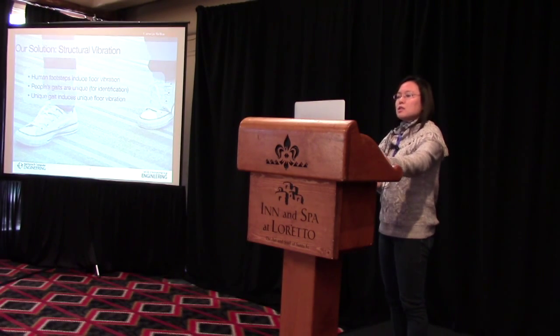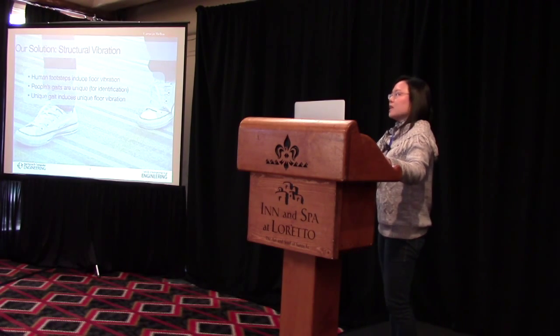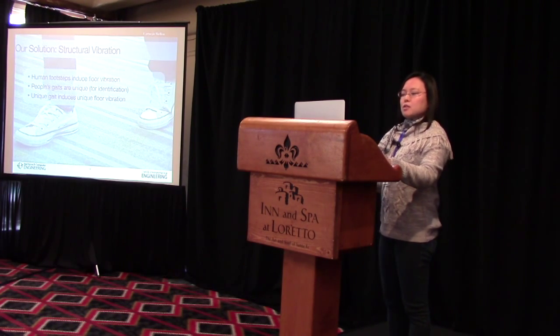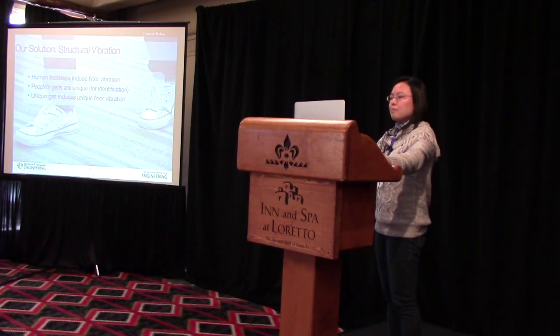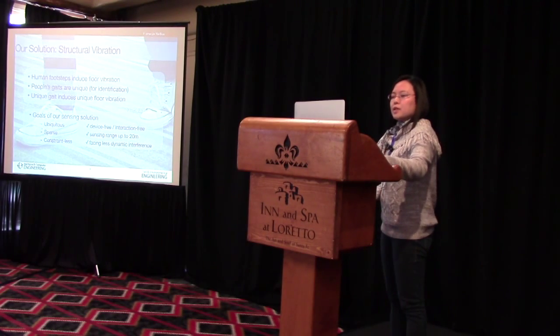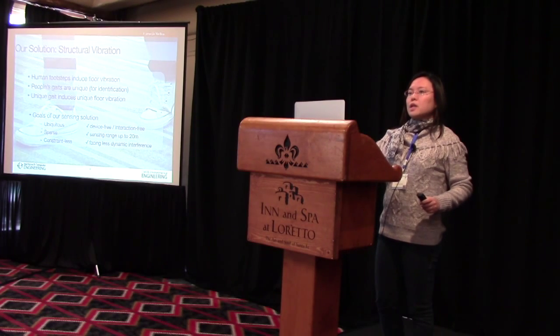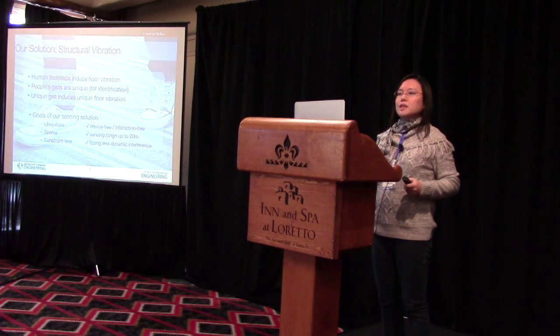We noticed that the structure vibrates when people step on it. Based on prior works we surveyed, people's gaits are unique enough for identification purposes. That means by measuring the structural vibration, we can identify people through the unique flow of vibration their steps cause. Therefore, compared to the methods mentioned before, the goals of our sensing solution are to be ubiquitous, sparse, and of fewer sensing constraints.